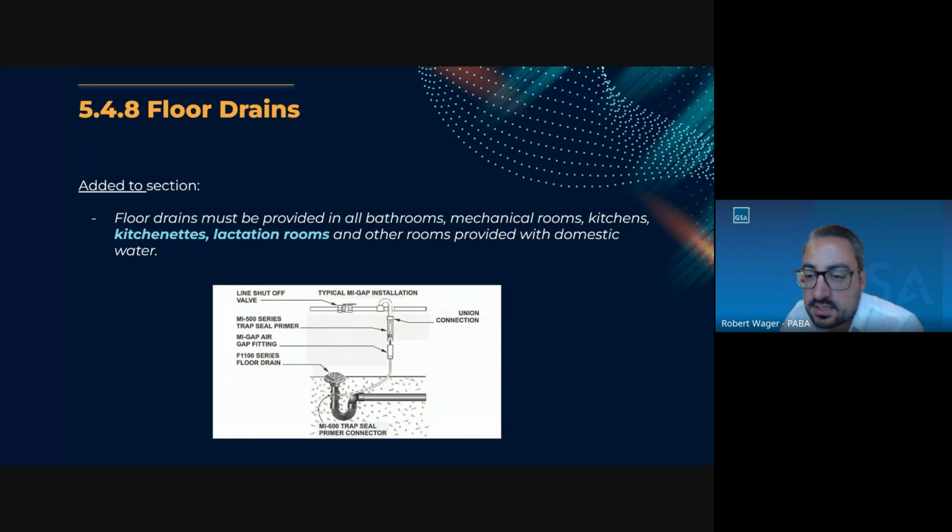OP says, is it to shut down the gas for heating of the water or a mechanical valve from the domestic water? OP, I believe you're talking about the leak detection. It could be both. It's more just to alert someone, an operator of the building, hey, you have a leak at this location, at this equipment, go check it out. And if there is sequencing language coordinated with that to trigger a shutdown, certainly that would happen.